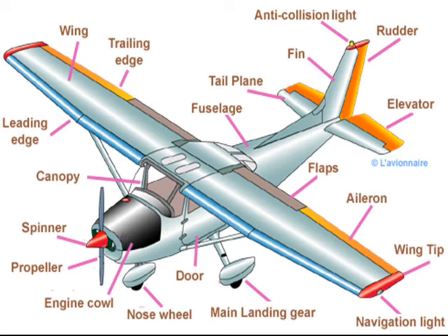We will move on to our next part, that is a propeller. The propeller, you can see here, these are the two propellers. The propeller is provided in the conventional piston engine as well as in the turbo propulsion engine. It has usually two or more blades which are driven round in a circular path. The blades deflect air backwards with an acceleration, and thus forward thrust is imparted to the aeroplane.